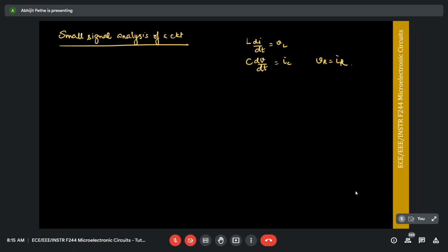Because if you look at our transistor model, it is not linear. It has a quadratic expression, right? ID compared to VG. And so what we are essentially doing, as I told you, when you do small signal analysis, is picking a bias point and linearizing the circuit with respect to it. That's exactly what we're going to do when we start analyzing circuits. So again, remember what a small signal analysis circuit is.